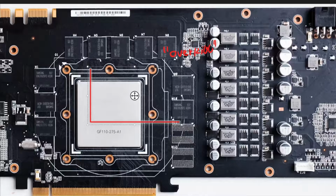So let's say that's time, and those are the amps that the GPU wants. So basically you're running a benchmark, and then a very, very intensive scene comes up, and then your current will basically look like that. And that's a current spike. And that's why the current ratings for those MOSFETs are so high, because they have to handle those spikes.